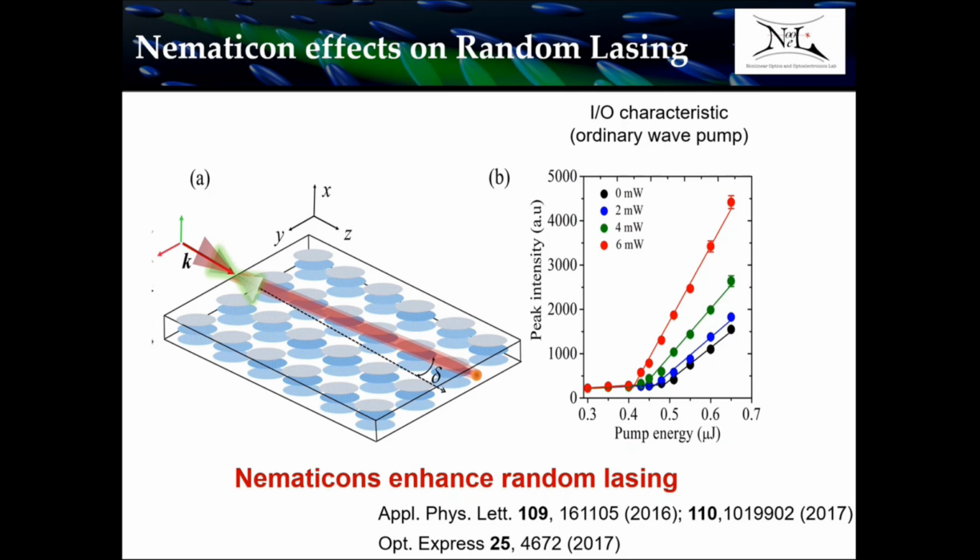The emitted light is confined in a limited volume given by this solitary waveguide, and thereby the interaction between spontaneous emission and pumping and amplification is improved, and so the laser, upon making a waveguide, gets a higher amplification with a higher slope of the laser emission after the threshold.